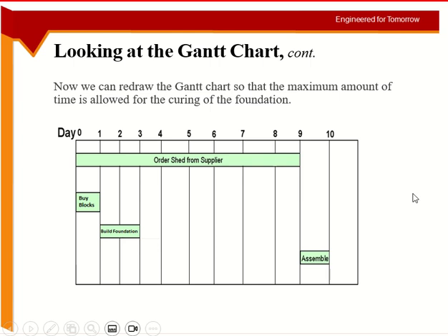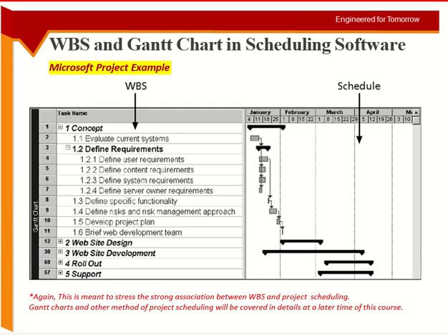So 7 days curing is very normal. You can still do the curing after that as well. But after 7 days, you can remove the formwork and the concrete is able to take some of the load. So this is what you need to keep in mind.